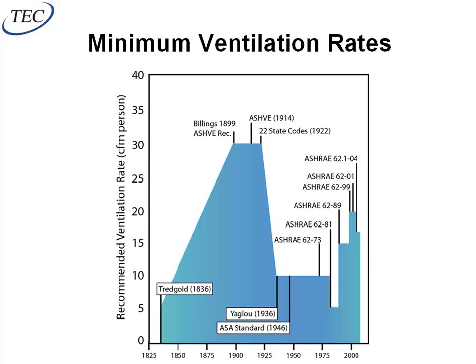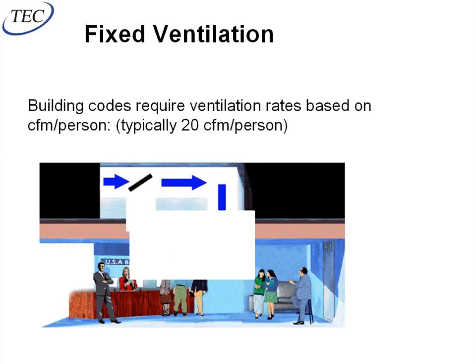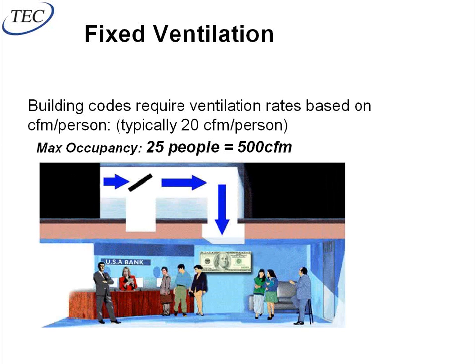Most of the rest of the building stock you deal with on a normal basis had the 10 CFM per person rate. So as you are rehabbing these buildings and gutting them and redesigning them and all that good stuff, chances are the ventilation rates are going to be double what they were the last time this building was properly engineered. So you need more ventilation air, and you want to be able to do that in the most cost-effective way possible. So this is a typical little project here.